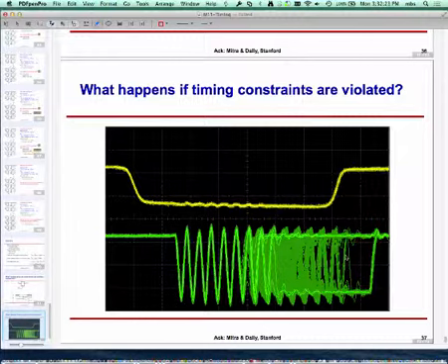So what they do is design these things so that the likelihood of violation, and therefore the likelihood of metastability happening, is lower than other causes which will bring the computer down. There are also other issues, such as software bugs or other outages that happen. So there's no such thing as it will never happen. It's just that the designers, across circuits and logic techniques, make sure that it happens rarely enough.